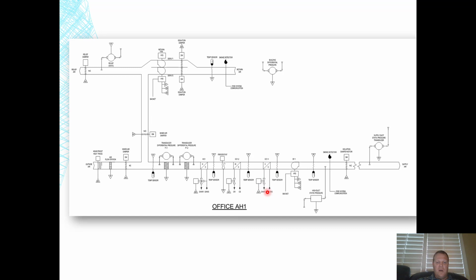Now, where did the water come from that got cooled off? It got cooled off at the chiller. But I need to show one more step, that the chiller needed to be able to cool off, to waste its heat somewhere. And in the system I'm talking about, it's going to waste its heat at a cooling tower.